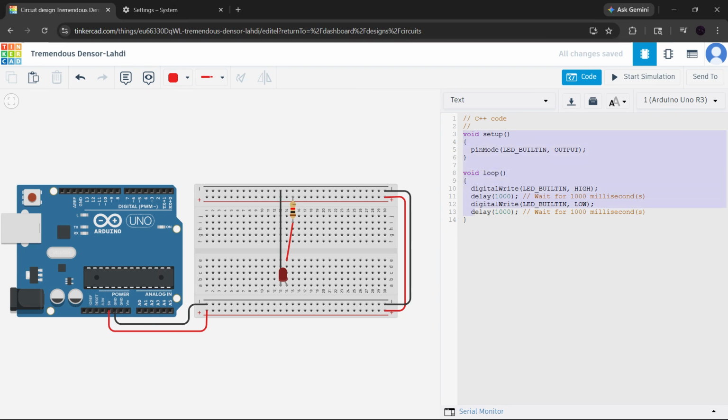If your circuit seems completely unresponsive, scan through the sketch line by line and make sure every opening bracket has a matching closing bracket. Also pay attention to your loops. If you have a loop or while statement running constantly without any delay, the simulation can freeze or become unstable, especially in the browser. Adding a small delay in the right place often solves the issue immediately. It gives the simulation time to process the code properly instead of trying to run everything at once. So if Tinkercad is hanging or lagging, check whether your code is missing a delay function.